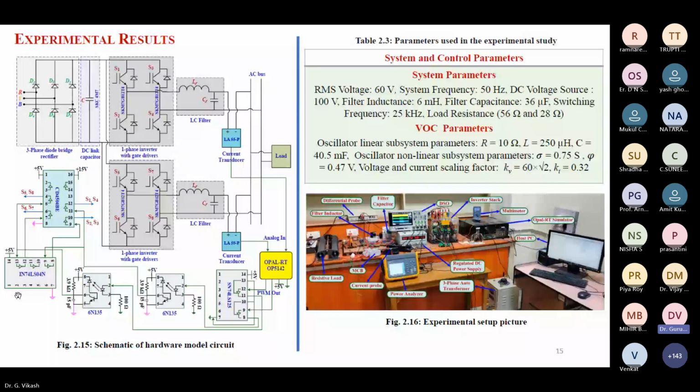If you go through the pin diagram or the manual of this gate, you can clearly understand what is inside the gate and what is happening. But simply you can remember, in the NOT gate you have to apply 5 volts across 14 and 7. Suppose the input is 13, the output is 12. If a 5 volt pulse is there, the 12 will give the inverted pulse. Similarly 11 is one input, 10 is the output, 9 is input, 8 is the output.